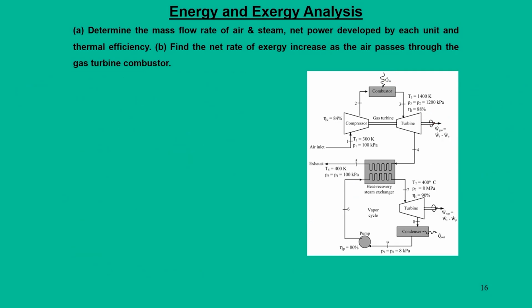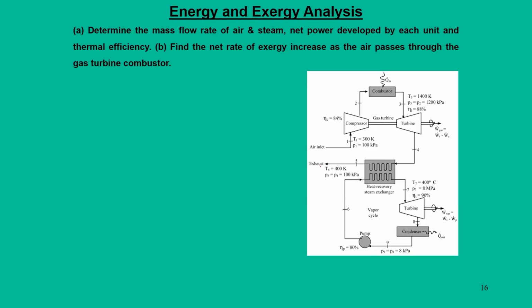Then we need to see whether exergy analysis is further justified or not, because that is essentially the backbone. We need to know, because this exhaust goes to the atmosphere, and the atmospheric conditions are P naught, which is 1 atmosphere, and T naught, which is 300 Kelvin, that is the dead state.